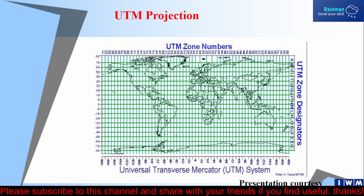For the northern or southern extremes, there are other projection systems. See, Bangladesh is above the zero line, so it is located on the northern side, in northern zones 45 and 46, divided by one line, here. So whole Bangladesh falls in UTM 45 north and 46 north.